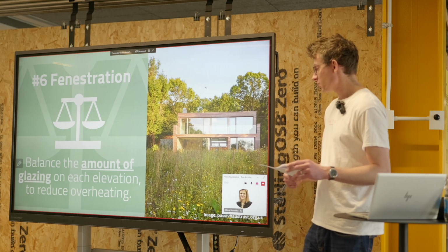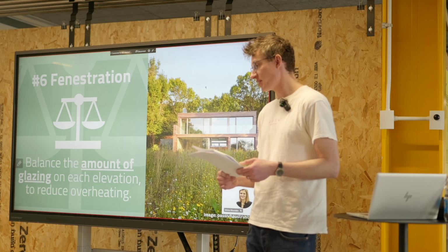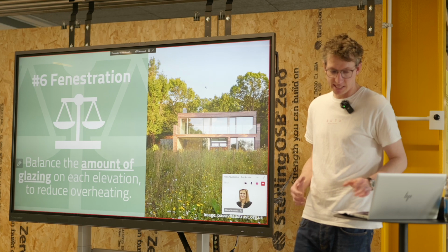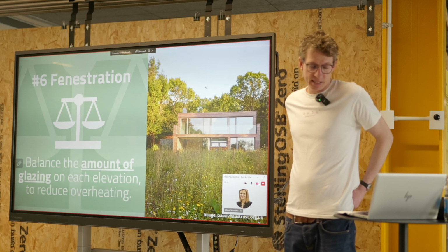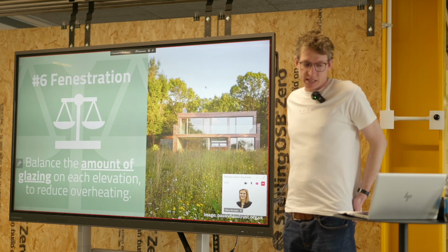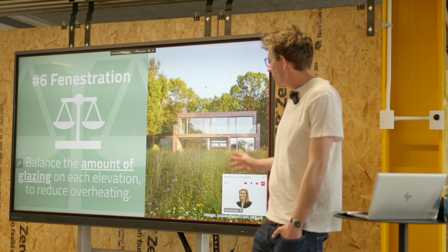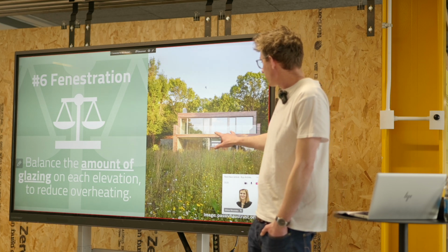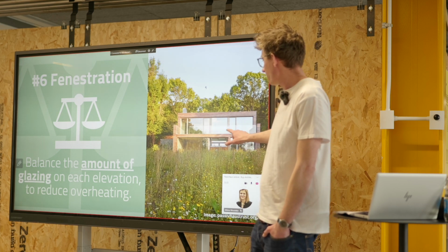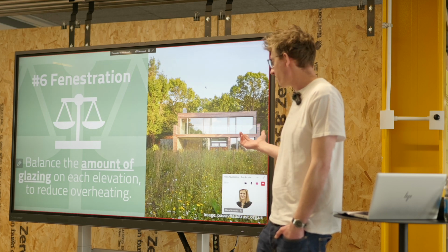So one strategy that you can use in passive house design or in any building design is to think about the natural ventilation of a building throughout those hotter days to create those breezes and cross flows of air. Something that's really important to consider is trying to design openings on different elevations. If you had two openings, let's say on this building facade here, and you open that door there and open that door there, you're actually not going to get very good cross ventilation because there's no differential of air pressure.